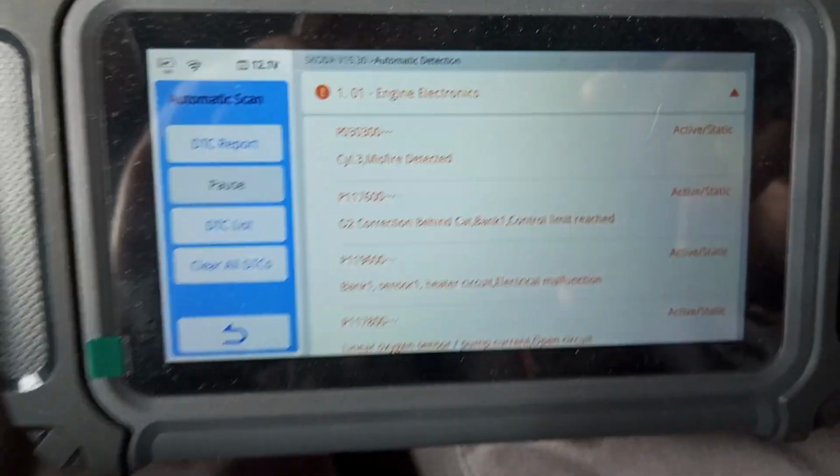But besides that, I also got a DTC code for a bad lambda sensor. And if I was to blindly listen to the OBD tool, I would go and change the lambda sensor, and I would be wrong. Why? Well, that DTC code for the lambda sensor originates from bad exhaust fumes that were caused by the engine misfire. After I finished everything, I took the car for a test drive, and in a matter of a couple of dozen kilometers, the check engine light was gone. And when I connected the OBD tool, so was the code for the bad lambda sensor.